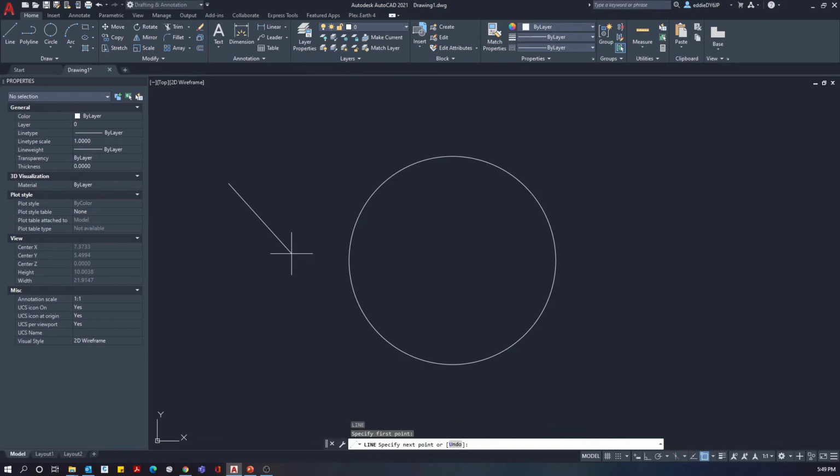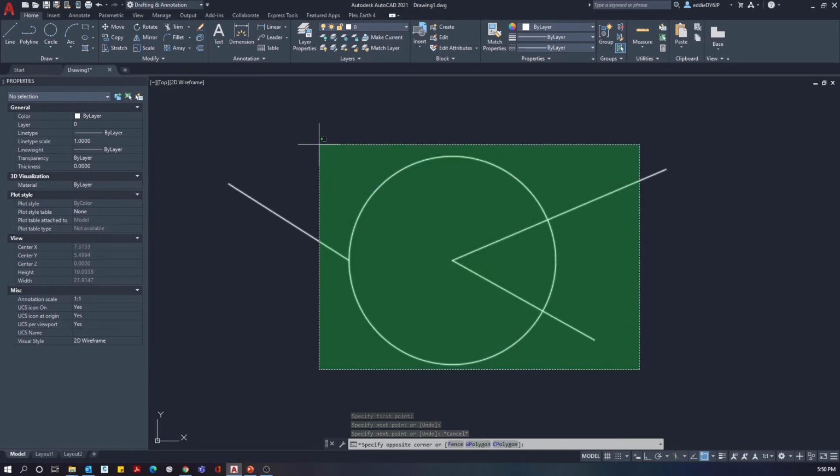Well, we can click, and if we want to get to one of the quadrants, such as the top quadrant, which would be at our 0 degrees, our 90, our 180, our 270, then we have those and they come up as that diamond. Or if we want to draw from the center of the circle or to the center of the circle, we can do that, and it highlights as a small circle inside of our larger circle. So that gives us our snapping point.